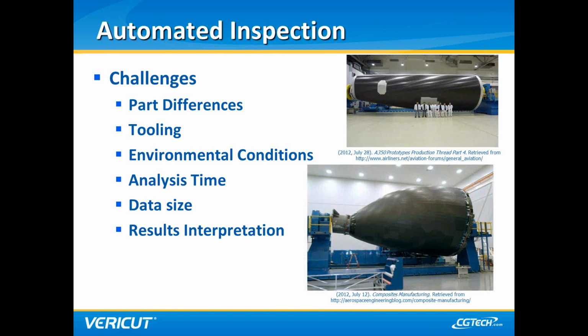Another one to think about is analysis time. So you can have this great scanning system. It collects a lot of data, especially on some of these large parts shown. But if you have to analyze that and perform your checks to see if you conform or not conform, and stop the machine before you lay that up, of course, over top of that, you need to make sure you're analyzing that with enough time to be able to stop the machine without slowing it down for production.